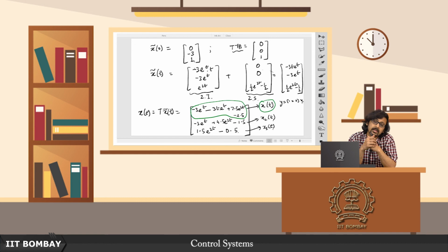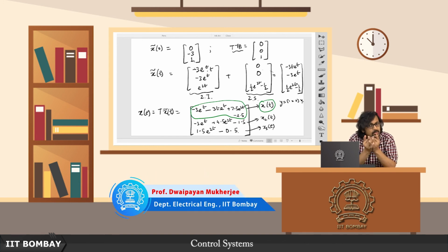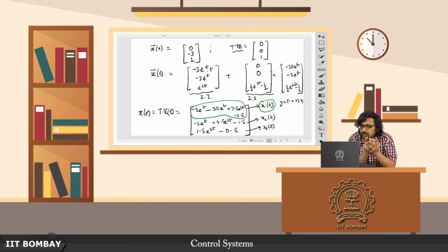Remember, the poles will only appear in complex conjugate pairs because the characteristic polynomial contains coefficients from the system matrix, and therefore the coefficients of the characteristic polynomial will be real, and any polynomial with real coefficients must have complex roots in conjugate pairs. Because we are dealing with physical systems, all our parameters are real, and therefore the entries of the A matrix will be real. That does not prevent eigenvalues or poles from being complex, but even if they do become complex, they will still appear in conjugate pairs, and that will hold the key, as we shall see in the next lecture.